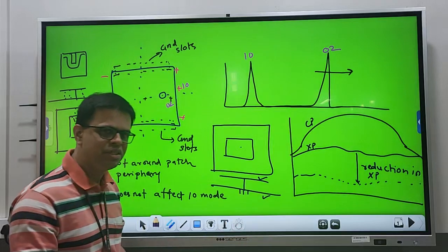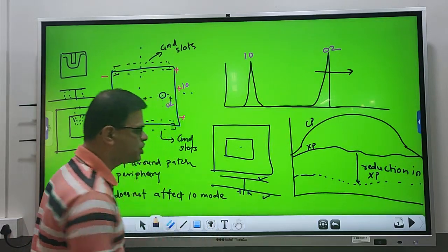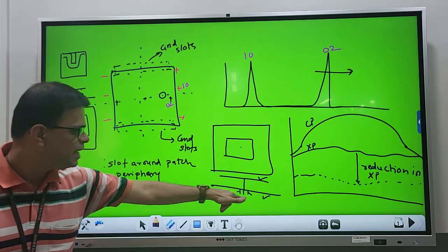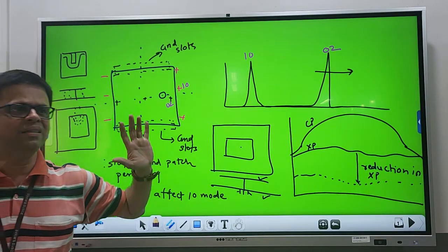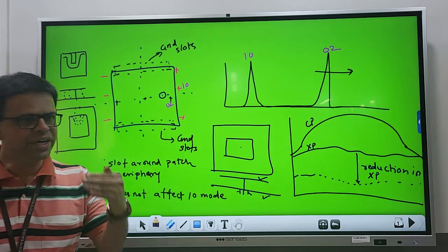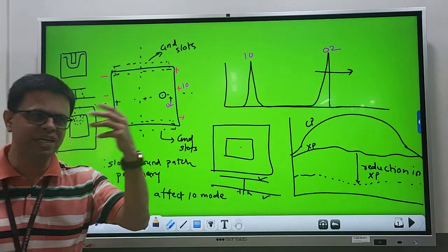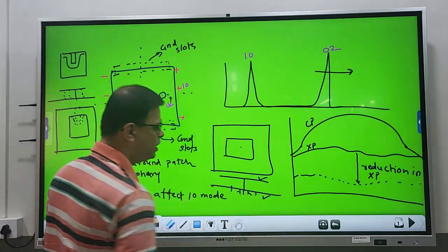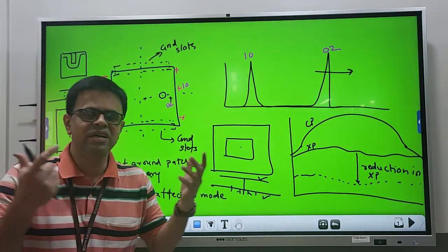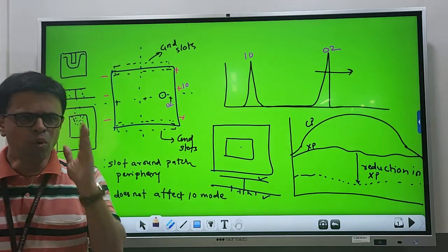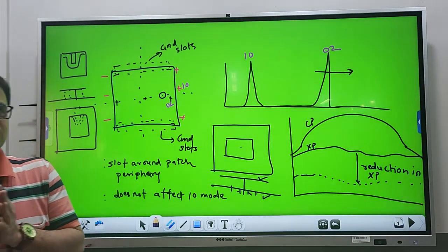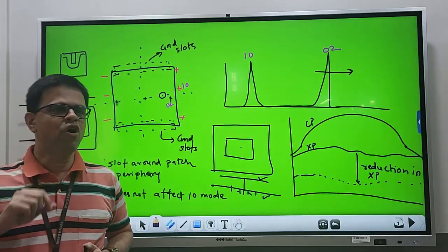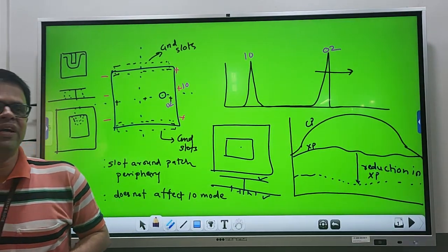Because how is the ground plane dimension identified? Because the ground of the coaxial cable is soldered over there. So that is definitely identified as a ground. So that dimension can also be lesser than the fed patch dimension. Of course, it offers certain antenna characteristics. Of course, it has disadvantages also. But you can create some modifications in the ground plane which can realize certain antenna characteristics. Moreover, the ground plane modifications have been exclusively evolved, exclusively understood for realizing a cross-polar radiation reduction.